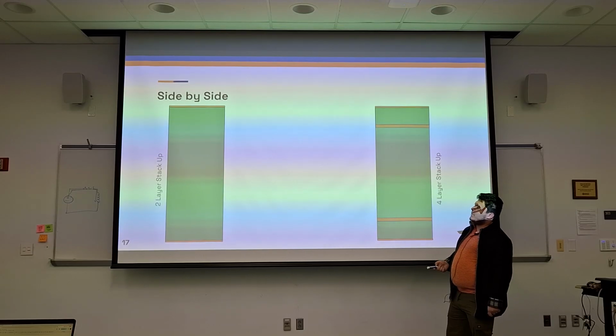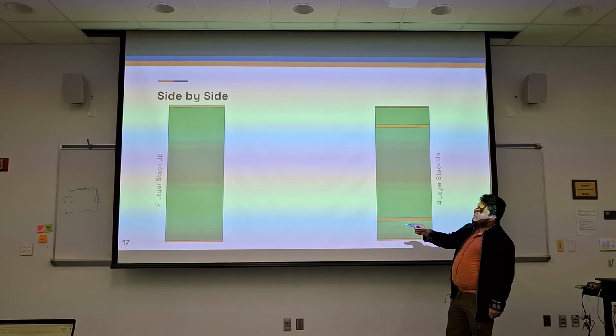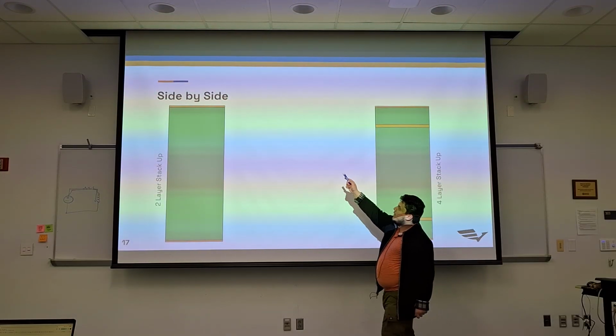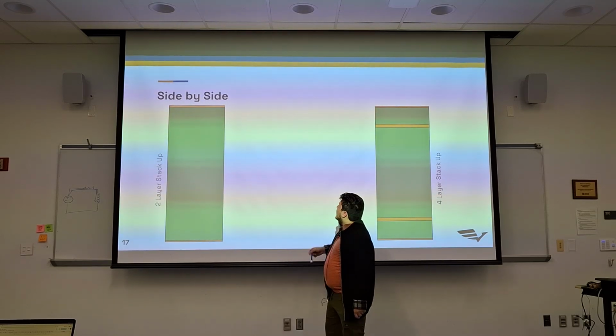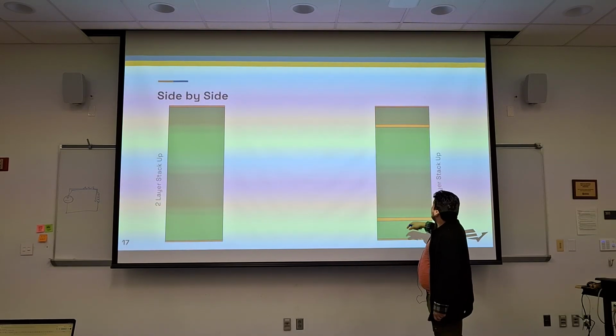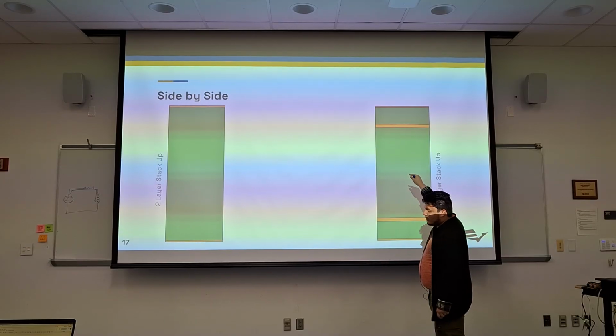Sometimes if everything is going to be via connections, this is going to reduce that because you're always going to have copper on both sides. Whereas if you have a higher layer board and you're only going from 1 to 3, all of a sudden your 4 to 6 is an antenna.